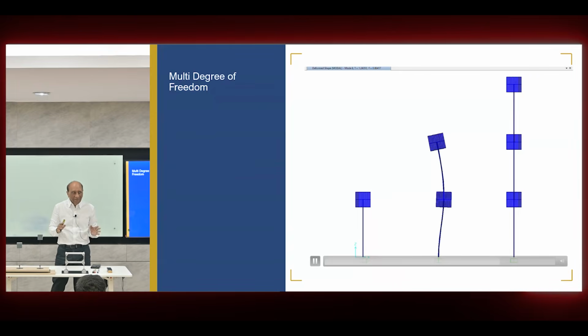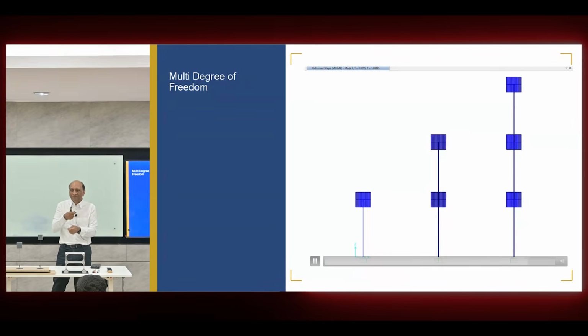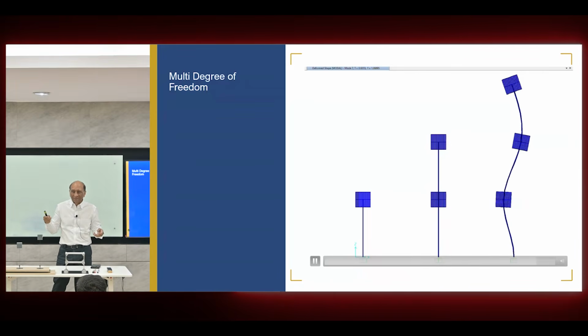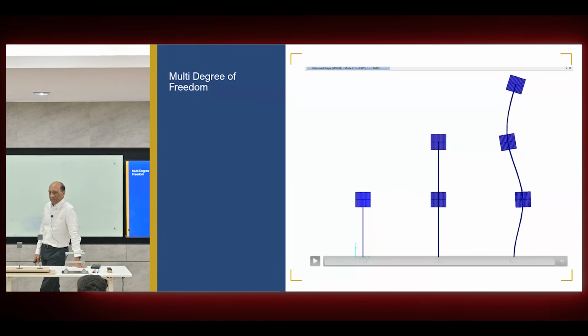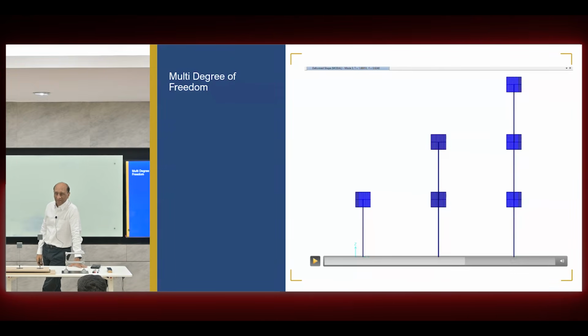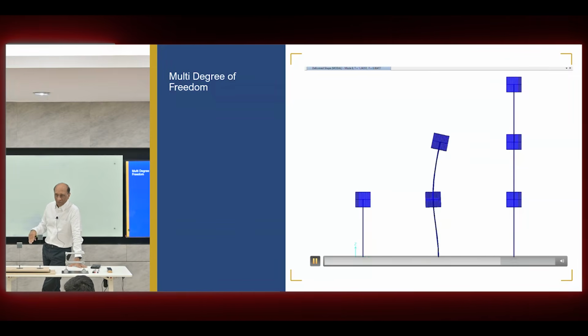After that is done, the higher modes will be where each mass starts to move independently, and that's what you see here. Now they will move in one single curve, then double curve, then triple curve, and as many curves as there are masses, right? And each has a greater stiffness and greater stiffness and greater stiffness. Each frequency will be higher, and the period will be smaller.